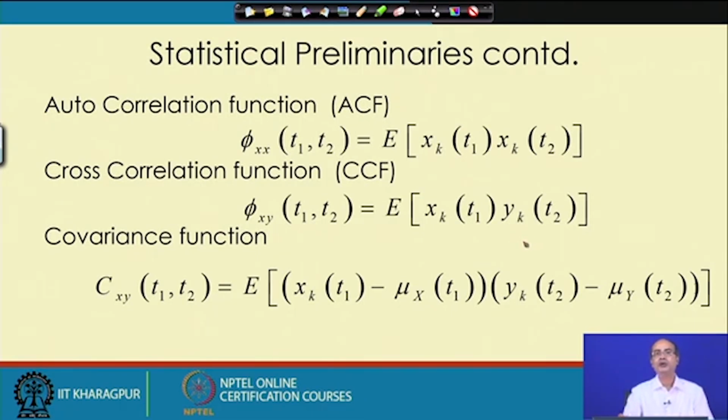And here one more thing we need to keep in mind when we are doing any signal processing experiment: unless the mean has some special meaning, we always remove the mean from the signal before doing any processing.